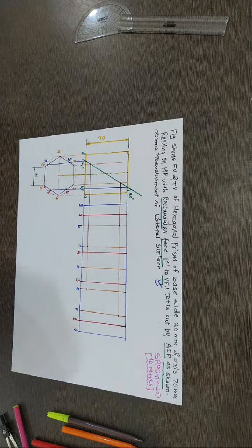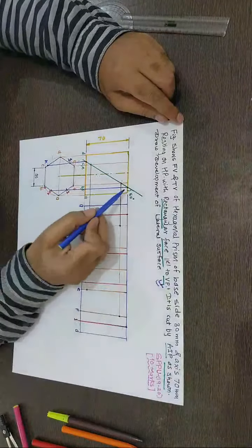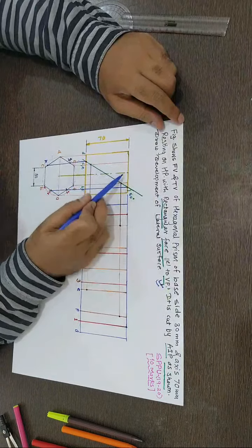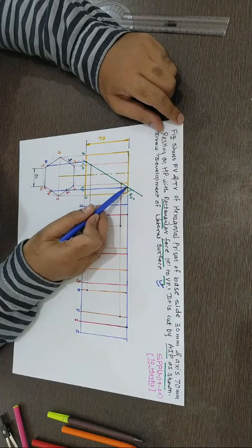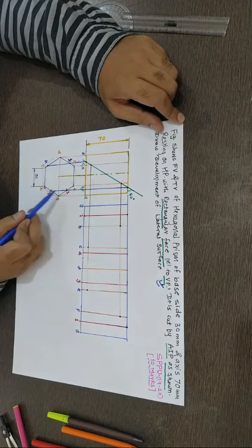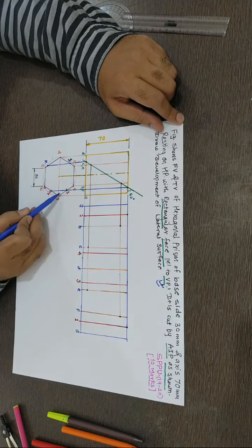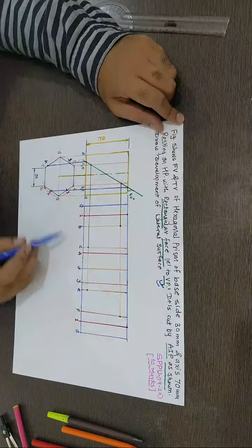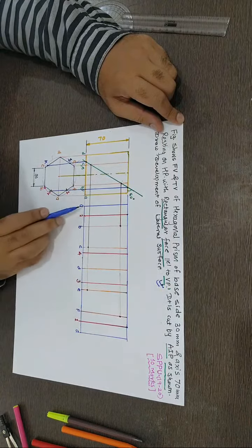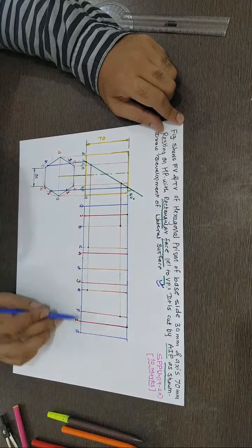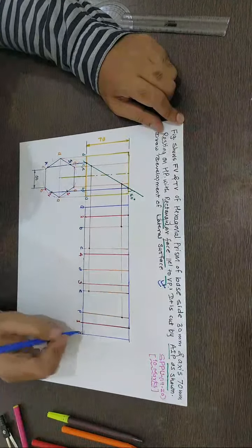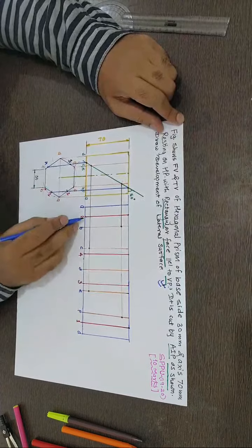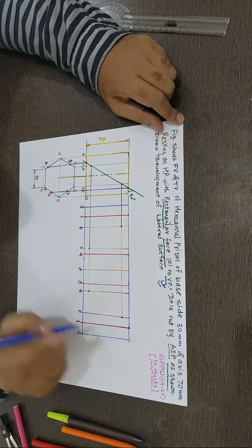Okay, so actually it was interrupted, so I'll just explain once again. This plane intersects the top face and the bottom face base. This point is projected here to get 1 and 2. Take the distance of 1 and 2 from A and mark from both. This is 1 in between AF, so no problem with notation. Take this distance, mark here from A, take this distance, mark here, to get the corresponding edges.